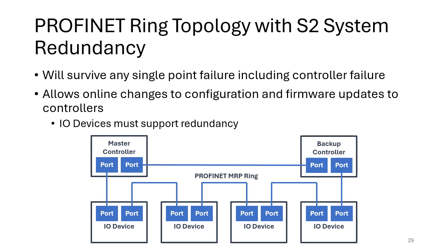I do see some devices which have additional network capabilities with more cables, but I normally run the availability numbers and they normally don't help you. There are very few failure modes where that can help, but generally, if you've got that high level of failures where multiple things are going wrong, you're probably at a more dangerous situation than just a PLC failure now. But this system, this is very good.